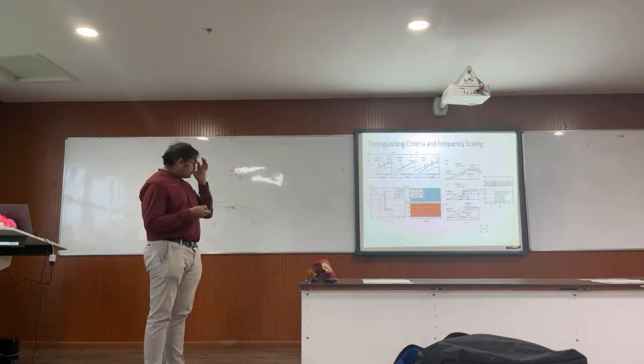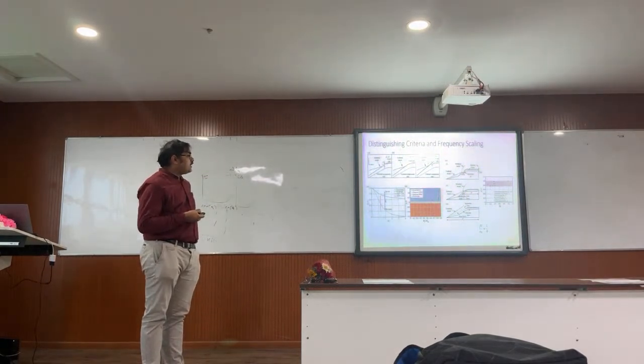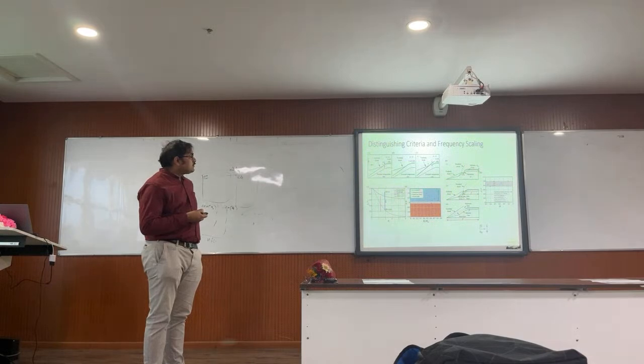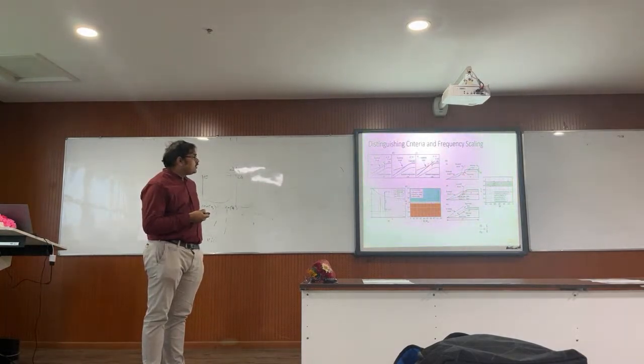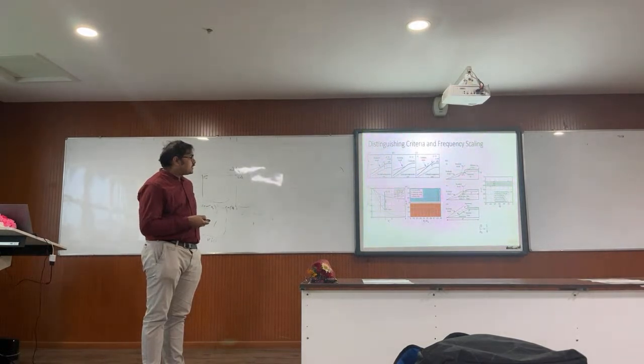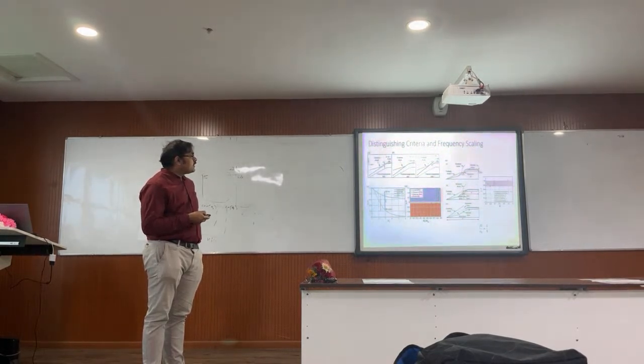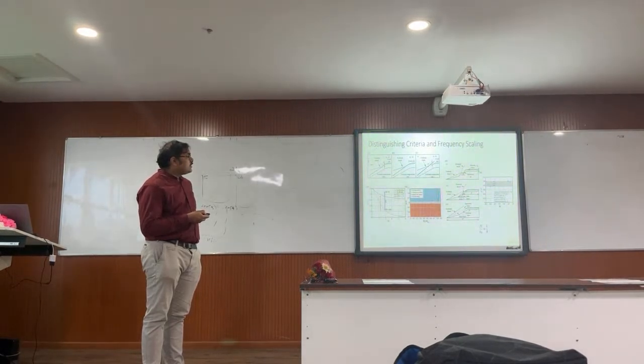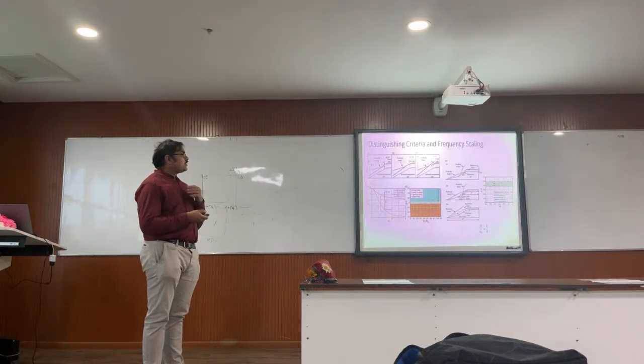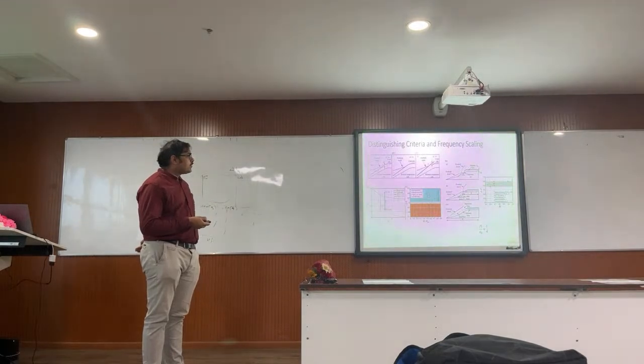And so we collated all those data and we looked into their schlierens, and we found that this shock impingement on the cowl has a very important role to play in deciding what kind of oscillations we get. If the shock oscillation goes and hits inside the cowl side, then we get very small amplitude oscillations, because here it is mostly dominated by the cowl side separation. These small amplitude oscillations generate a shear layer and then give a cutoff. While if the shocks lie just outside the cowl, then they produce very large amplitude oscillations. And if they sit just at the cowl, it forms the boundary between these two.